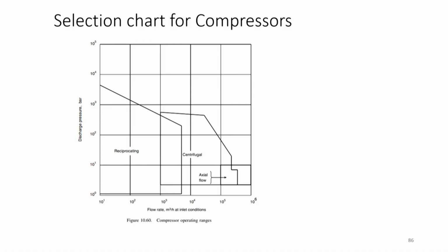Another one is selection for compressors. Based on the pressure ratios and the flow rates, how do you know whether you want to use an axial compressor or a centrifugal? So if you add this level of detail, like Professor Mahajani said, this is what comes after a simulator. But this is the real design. If you have a really small flow rate, you can't use an axial compressor. You have to use something else, right? How do you know what to choose?